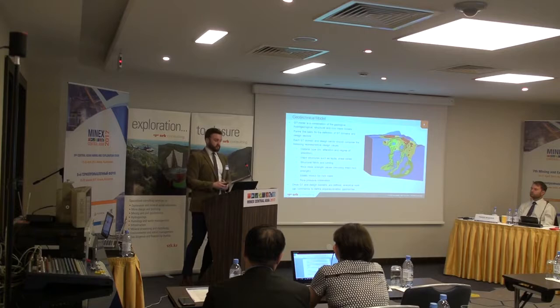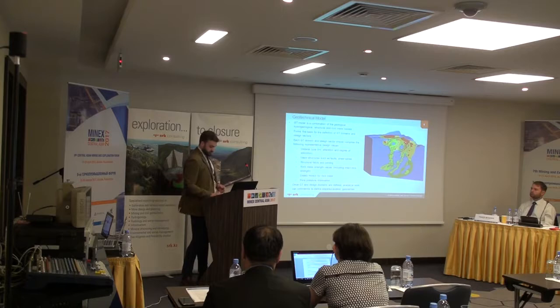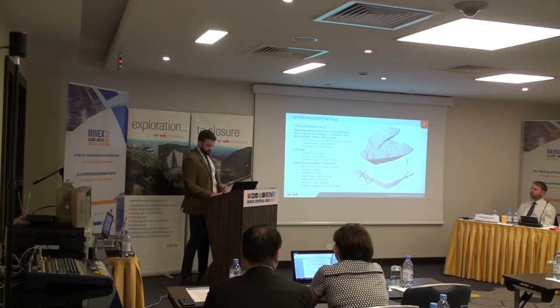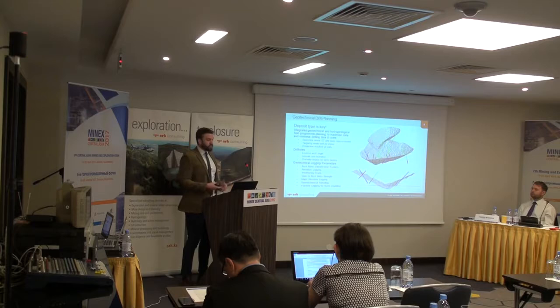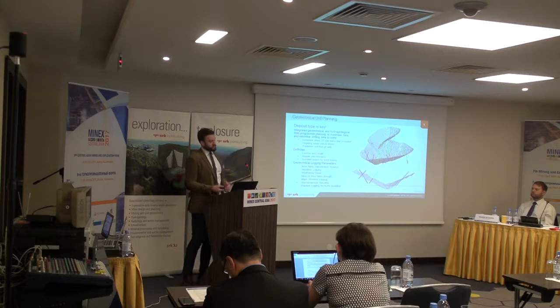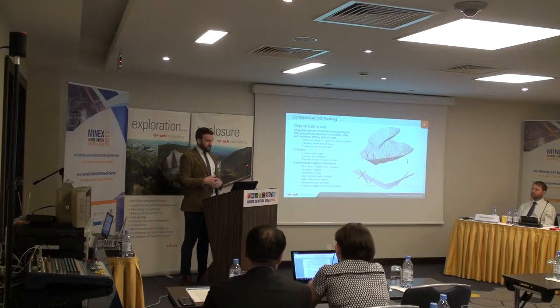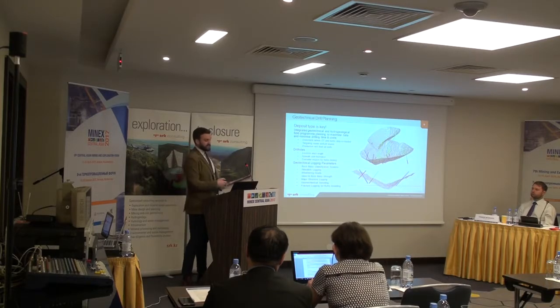So that brings us on to your geotechnical drill planning and field investigations. And the one thing that I've highlighted here is that your deposit type is the key. You need to understand if you're working with maybe a copper porphyry where you have a column-shaped mineralization, or whether you're working with a flat-bedded phosphate deposit or coal deposit, or whether the deposit is a shear-hosted gold vein, because that is really what will drive how you plan your geotechnical drilling.